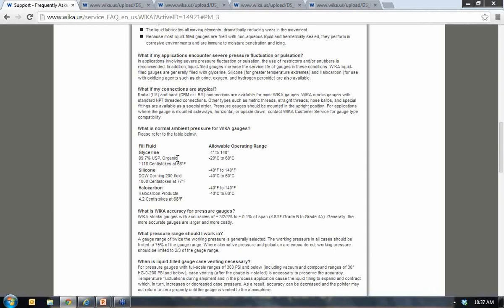Next question, can you explain about pressure gauges with a pigtail? Any advantages or disadvantages? The pigtail being the pigtail siphon. This is the original siphon technology. The newer technology being that short mini siphon that I referred to in the presentation. The pigtail siphon and any siphon really must be installed correctly in steam or process applications. The point of that siphon is to introduce a volume of liquid media. I'm going to use steam as the example since it makes the most sense.